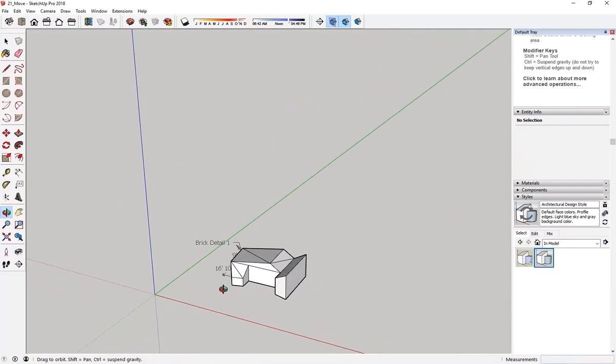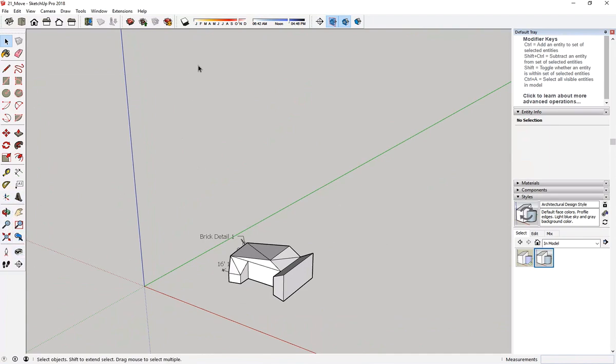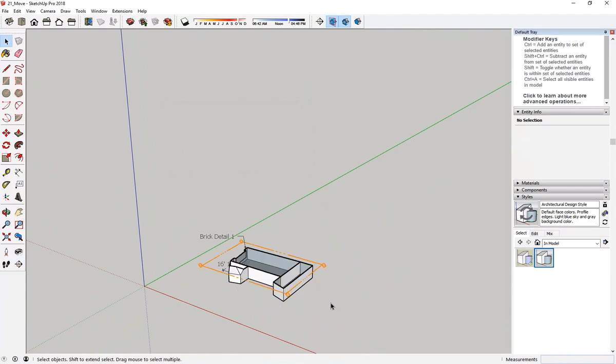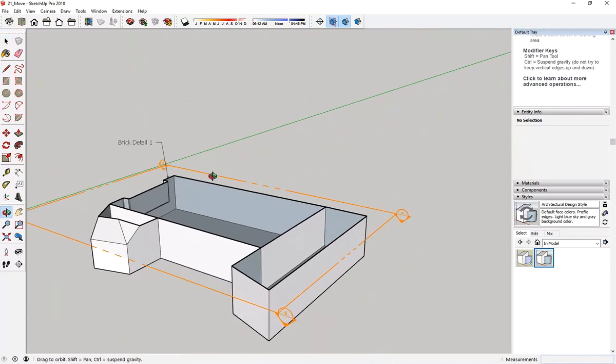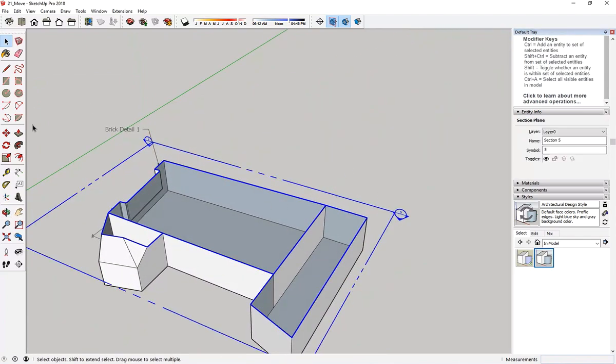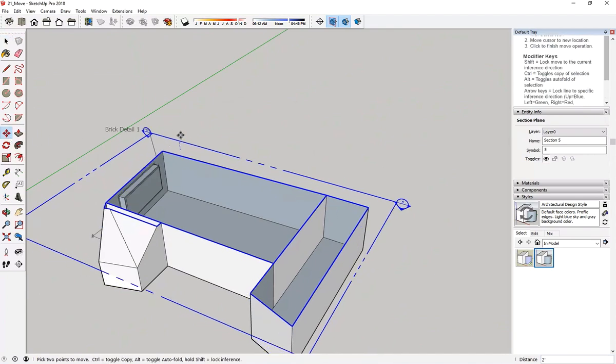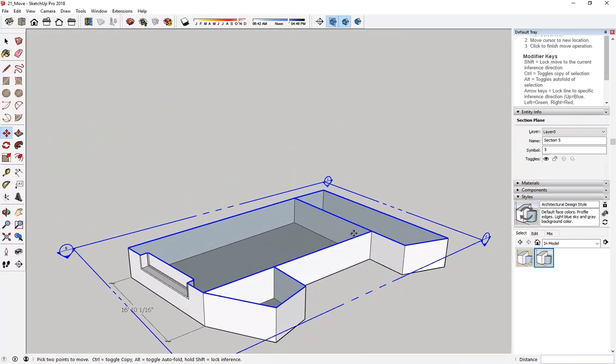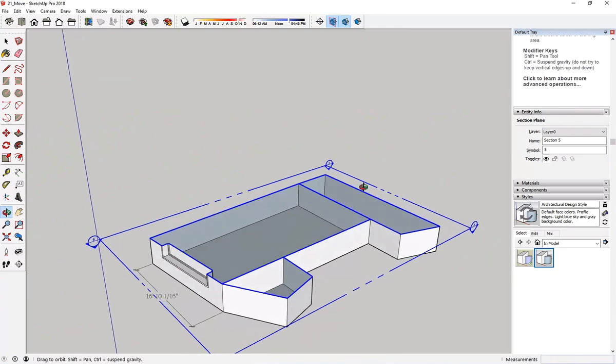So as I mentioned, for creating the floor plan, the only thing that you have to do is that when you are working with this section, you have to make sure it's outside, under a plan view, and then hold shift and then bring it to your geometry and click somewhere. And then when you have that, same as what you did with the other type of section, we can use the move tool in order to bring this up or down in order to adjust it at the right level. So right now we have only one level, but sometimes you might have multiple levels, so you need to change this according to that.